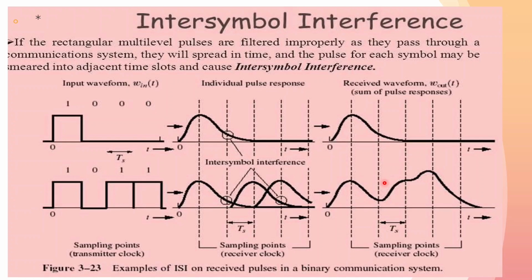In this unit we are going to take care to prevent this intersymbol interference from occurring, and in subsequent topics in this unit we will also use this intersymbol interference concept to save bandwidth, that is, to increase the number of bits, in correlative coding, but there we will introduce intersymbol interference in a controlled manner.